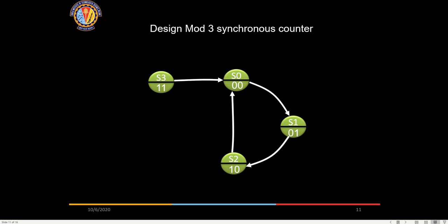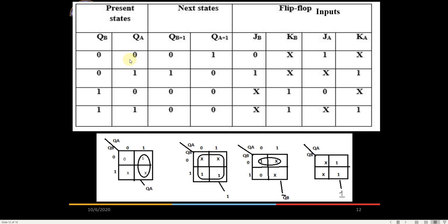Sir, maybe if only 1 bit is changing, then we can go. No. Say even for this circuit, let's assume I require first 0 0, then 1 1, then 0 1, then 1 0, then 1 0 1 again, then again 0 0. Can it go like that? Yeah, we can do that, right? In fact, it doesn't impose any restrictions. For all these 4 combinations, we will write 0 1, 0 1, 1 0, 1 0. From 0 0, what is the next state required? It could be 1 0, it could be 1 1, doesn't matter. Understood?